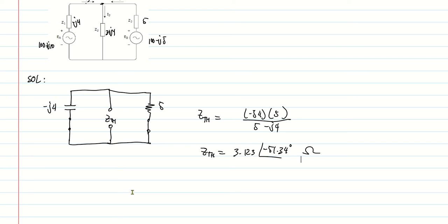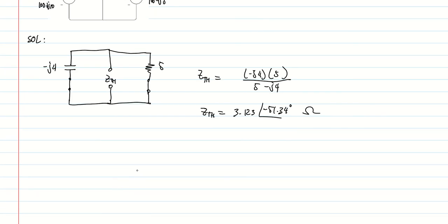After solving for ZTH, the next step is to determine our voltage, VTH. We bring back our sources in the circuit, but still don't bring back the load.